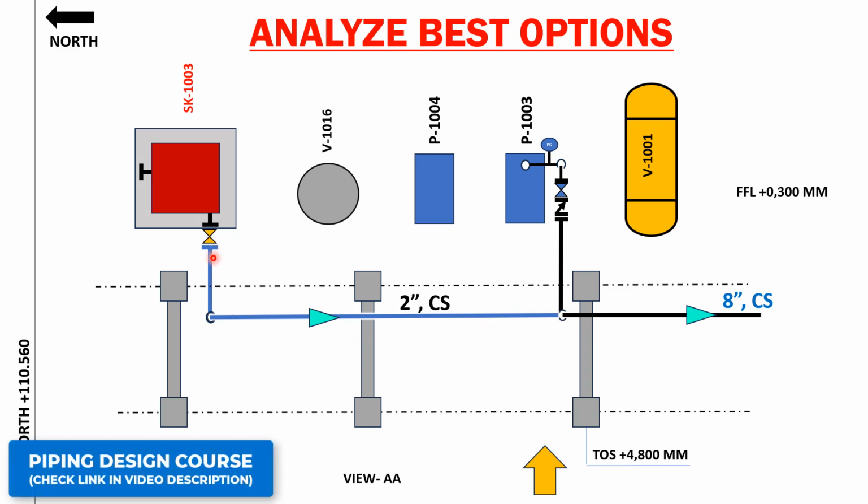So whichever is the easiest way that I can connect. What I'm feeling is that instead of dropping the line here, taking a turn here and going here and connecting here, it is more complicated than connecting directly over here. So my thought process is that I can avoid some of the bends, by not putting a lot of elbows. There will be pressure drops that I can avoid. I can directly connect the line over here. This is my proposal, but there will be some issues, right? You have to analyze those issues.